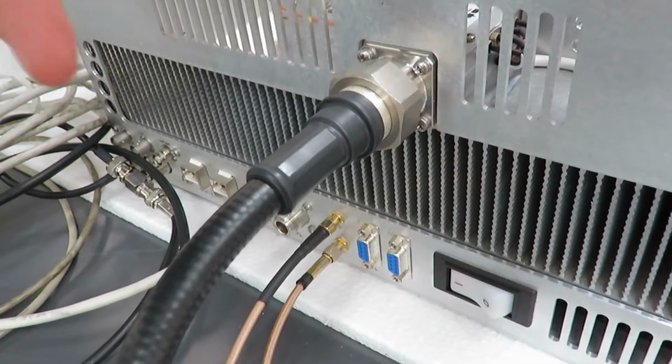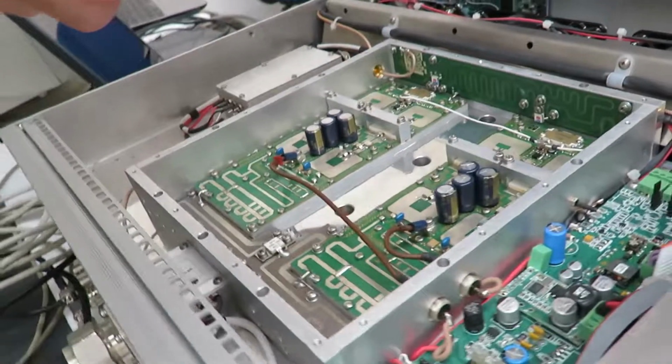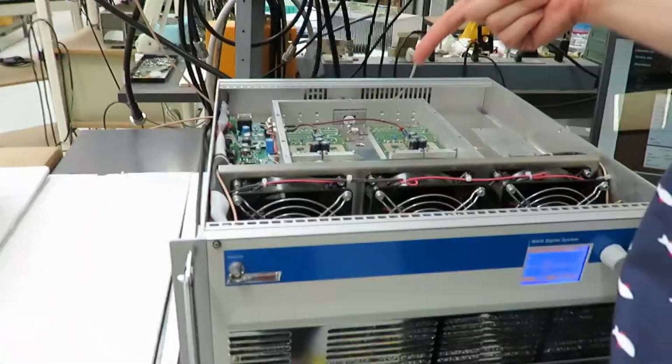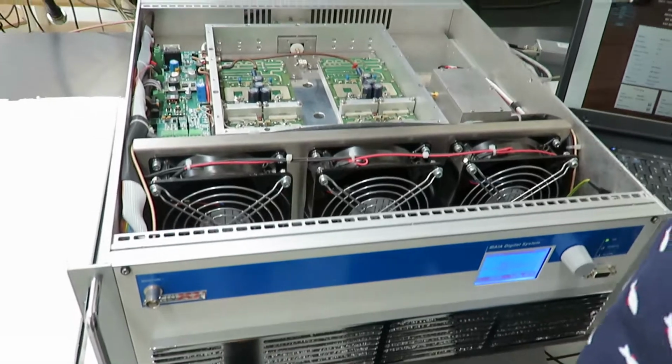The output connector is a feeder cable with the 500 watt RMS signal, which then feeds the output cavity filter here. And of course, the output cavity filter then goes to a dummy load, just to put power into a 50 ohm load and avoid any reflected power. But it's good to have a detail of the Doherty technology.